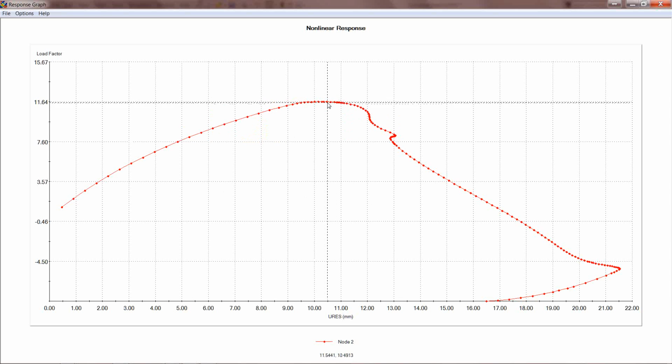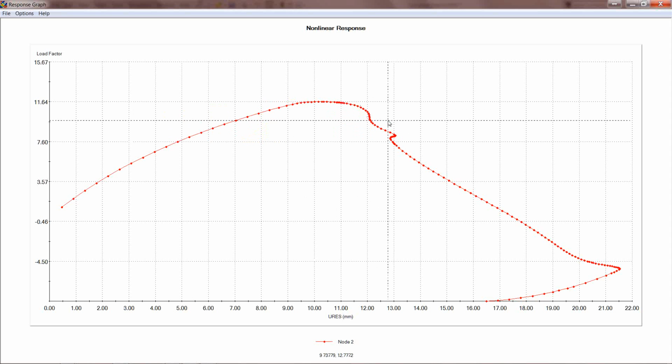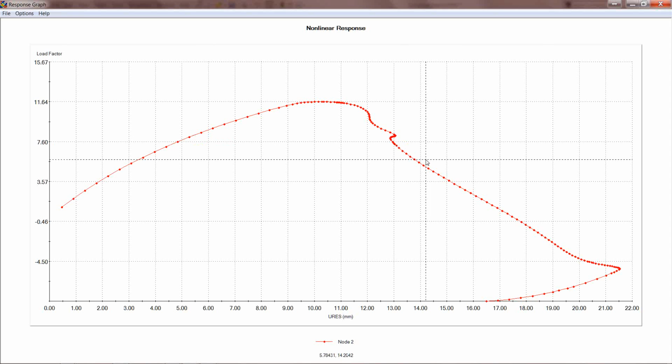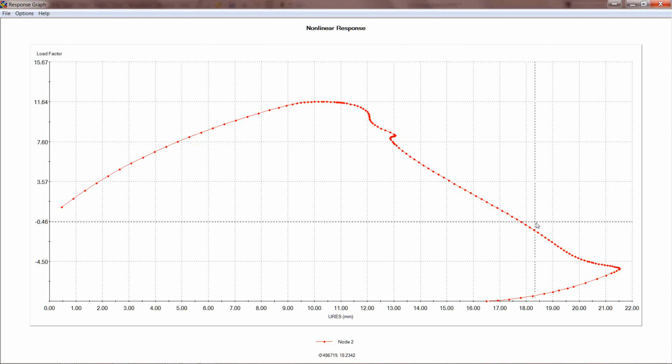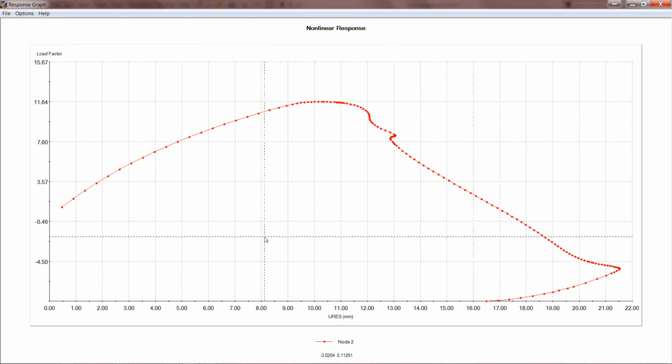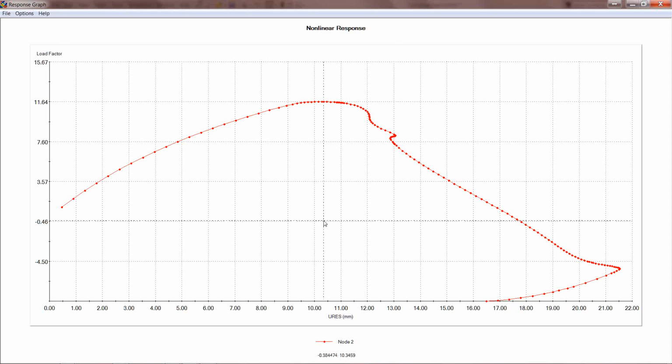We're starting to buckle, and then it goes into buckling. This is the outer edges of the sheet going into a secondary buckling mode. It then reaches this kind of unstable point of equilibrium where we have this snap-through, and then the displacement decreases again as the buckling continues.